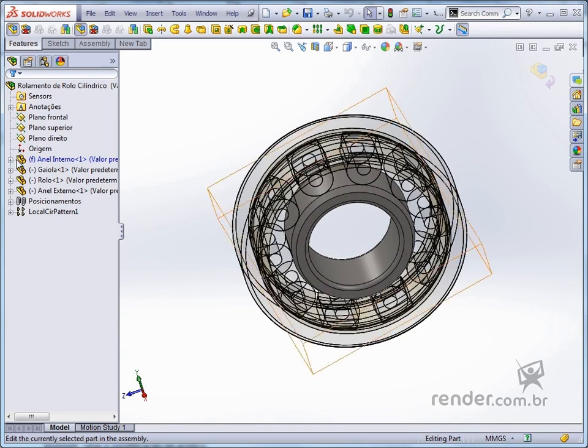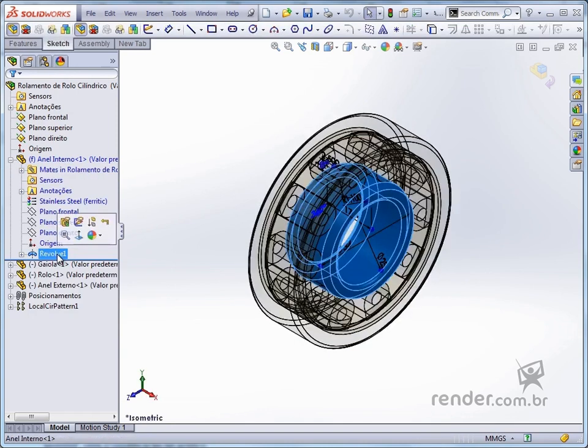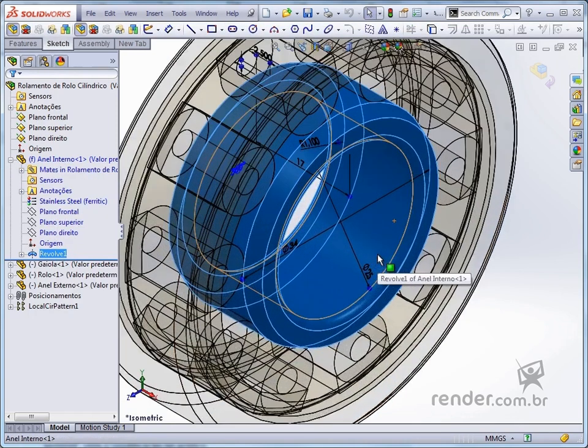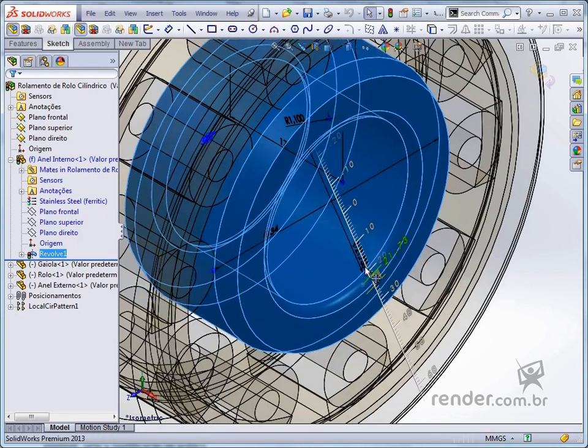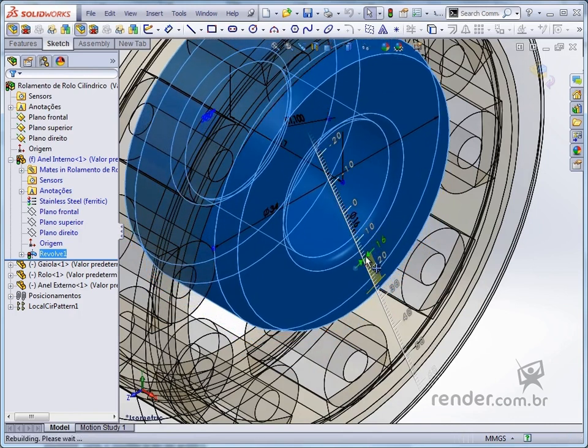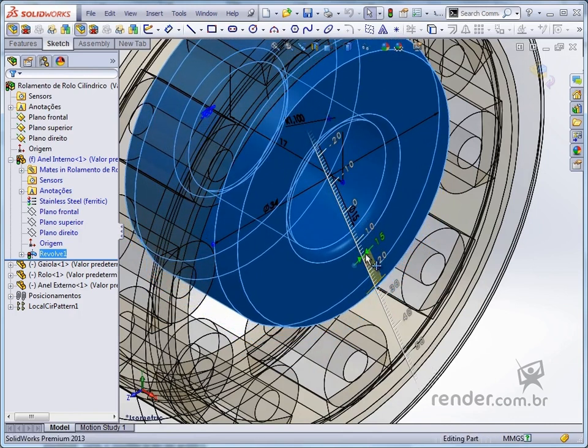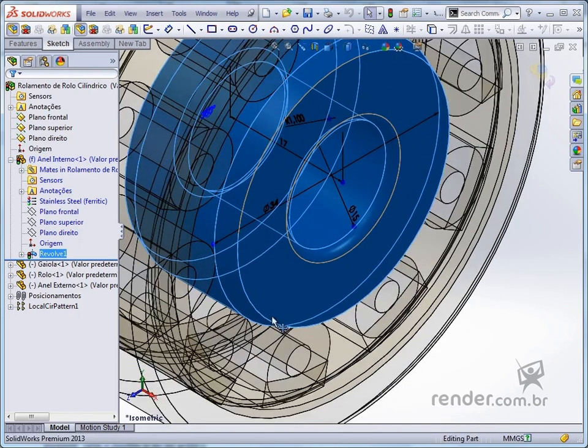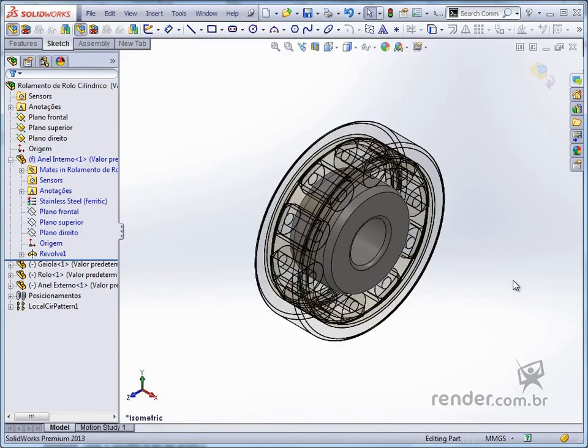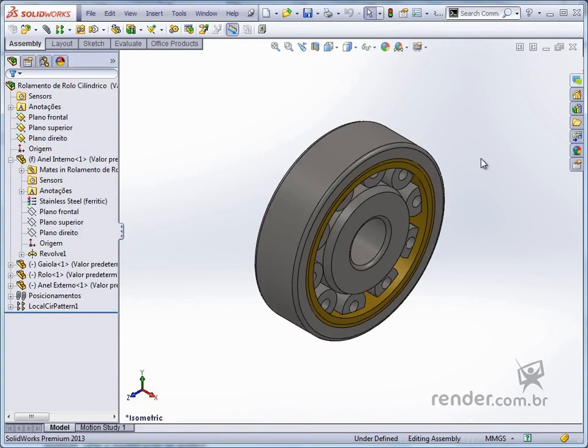We click on the Revolve feature and see that the dimensions are displayed. Through the blue dot, we decrease the diameter from 25 to 15 mm. Note that the part has been updated. To exit component editing, click Edit Component on the toolbar or on the Confirmation tab. Note, the assembly has been rebuilt normally and displays the updated part.